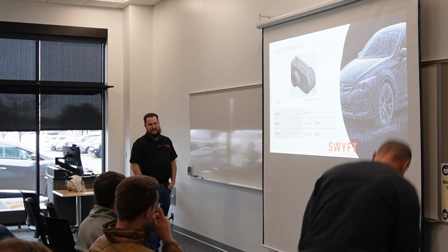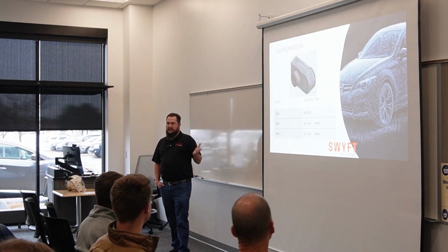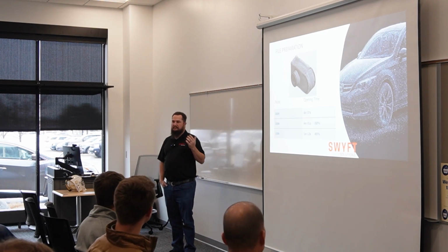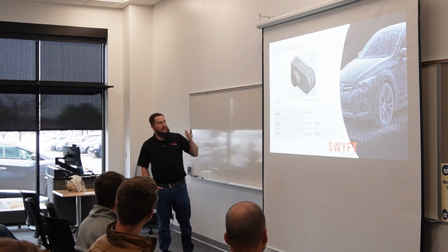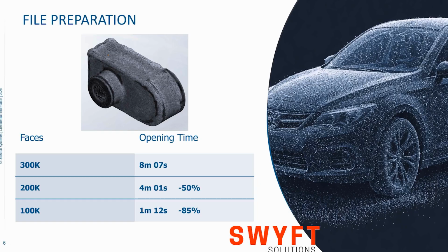The important thing is how many faces and facets your model has. Depending on your scanner settings, this could be a huge number, could be slightly less, but most of them are going to be more than SOLIDWORKS can reasonably handle. This basic model here, which is a little 6-inch part with a cheap Creality scanner, put out about 300,000 faces. If I tried to open that in SOLIDWORKS, it took a little over 8 minutes to open on my computer, which is not a powerhouse, it's just a standard laptop. But it took 8 minutes.